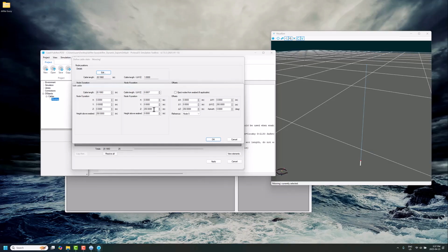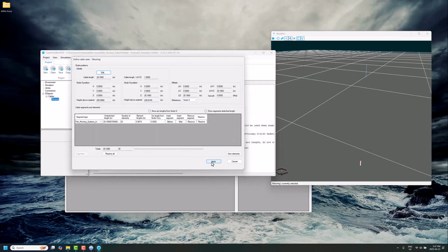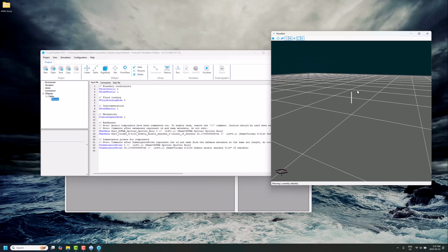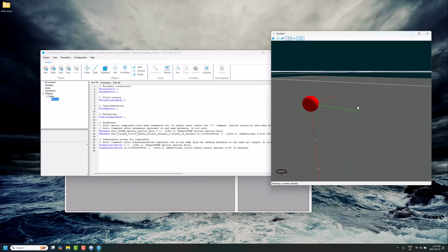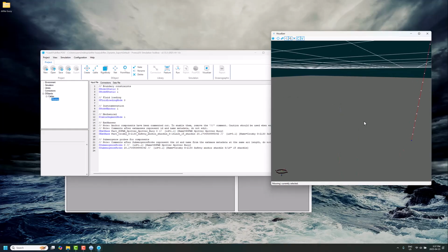There's a couple of things you can do here. What's really quick and easy is to use the deltas on the side here relative to node N. Got the length here of 20 and a tiny bit, so I should put in 20.186. I'm just copying the number of the length that's configured there. And we'll go to Proceed and Apply, and then you'll see over here, boom, there's our drifter buoy starting off at the water surface. There's our little Sofar buoy. So that's great, starting there.